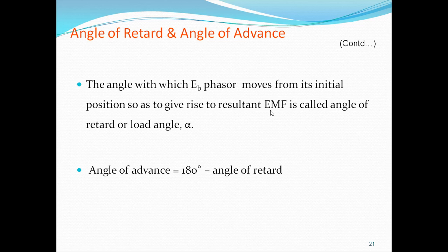That is starting torque, and next one is running torque, and next pull-in torque, and next pull-out torque. So we noticed four torques. What are they? When the motor comes out from synchronism, at that moment the torque developed is called pull-out torque. The torque produced at the time of starting is called starting torque.